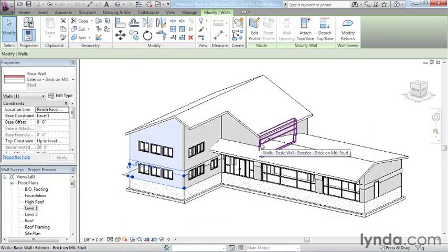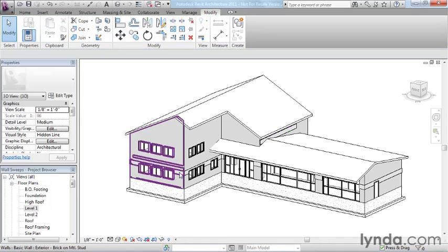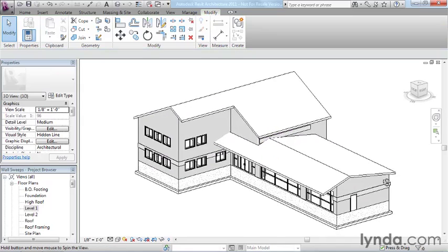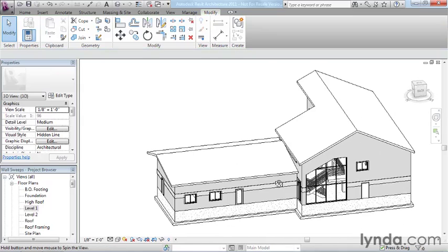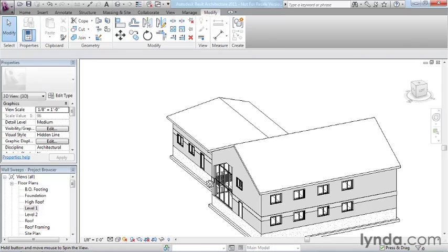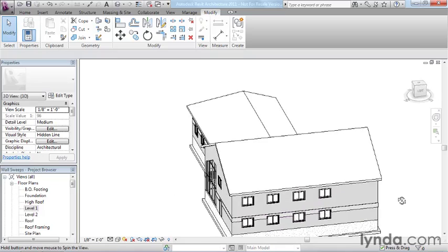The reason we're seeing it up there is that that's a new wall starting at the second floor. So now the soldier is measured 6 feet from the second floor. So I'll leave that to you to remedy. You just swap in a different wall type up there. But you can see right here that the soldier course wraps all the way around the building. And that's the result of doing it as a type level setting. You can also see that because we made it cuttable, the windows and doors are cutting through it.